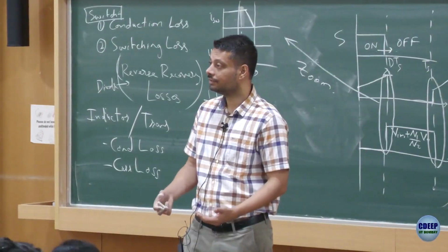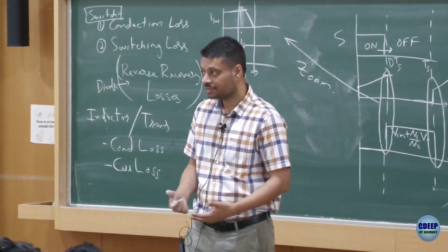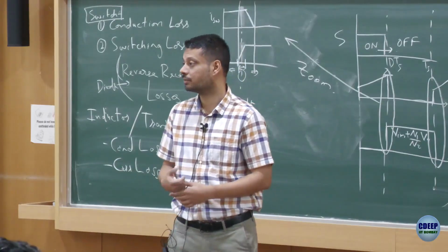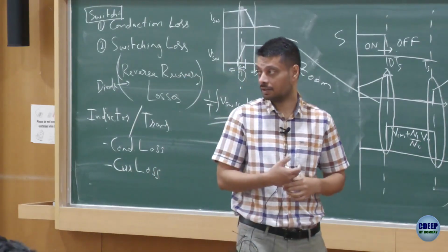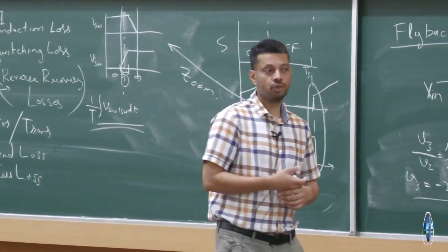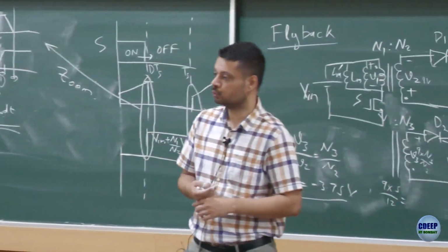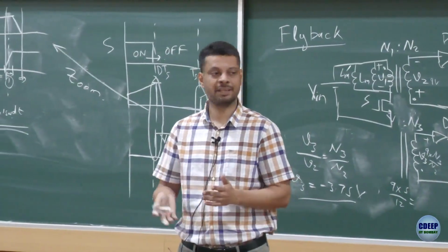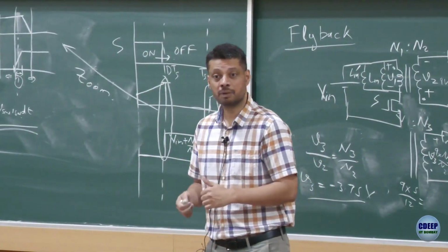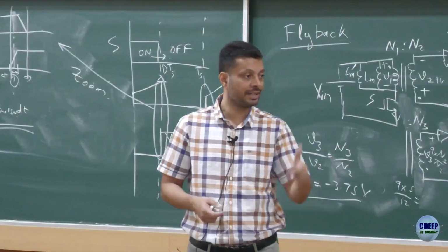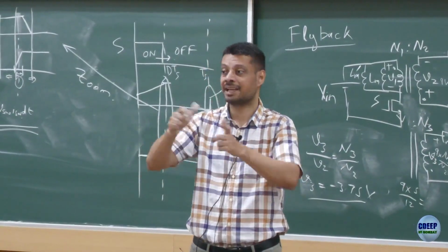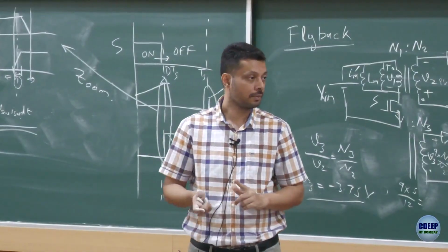What are you saying? Higher D, boost is not most desirable because as the D increases, your losses become more in fact in a boost converter. This is what we saw. Maybe you are saying the other way around probably. Yeah, so you would not use buck boost, you would use boost, right? If you want to buck the voltage, you would use a buck converter, you would not use a buck boost converter. You would only use a buck boost converter where the input is fluctuating or the output is fluctuating, so that with the same circuit sometimes it has to buck, sometimes it has to boost, right?